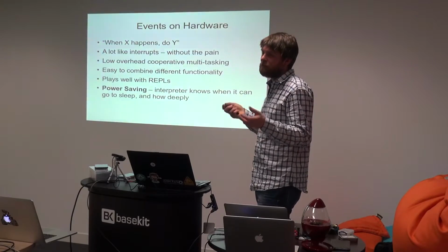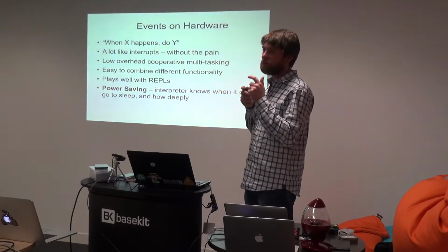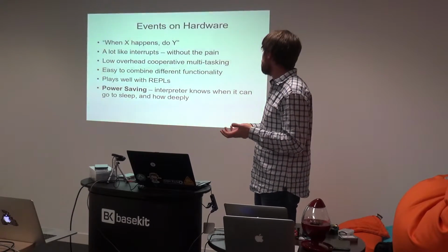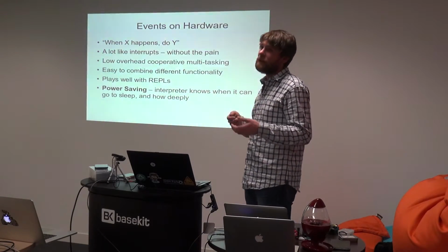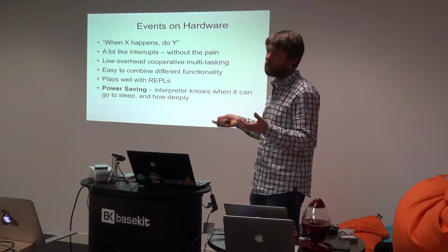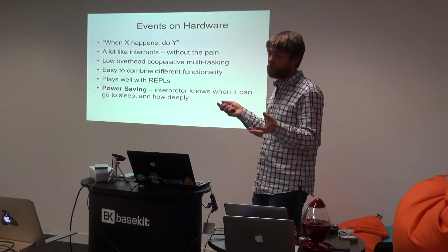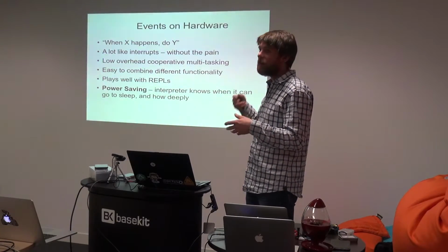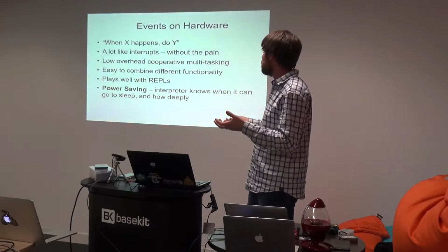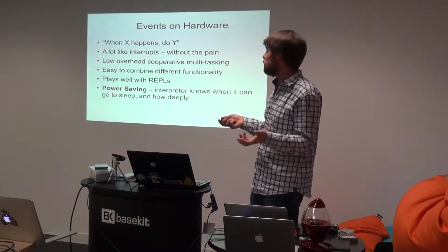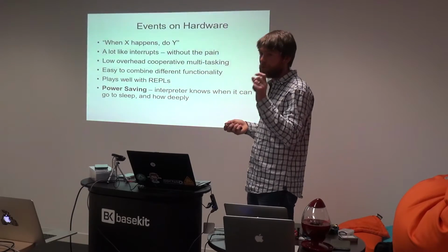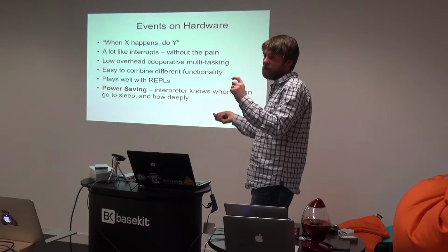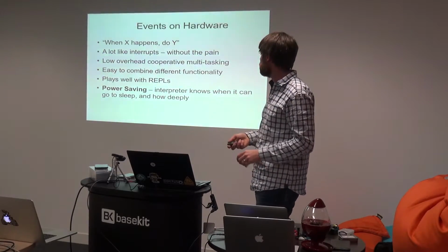If you just make very, very small functions that are executed as and when they're needed, you get a certain level of multitasking for free. It means that you don't need a separate execution stack for each process, and everything just works really nicely. The REPL that you saw, where you could enter commands, is running alongside everything else in the system, but without proper multitasking. It's able to do that because all the tasks just leave when they're done and schedule a function to be executed for the next part of them.